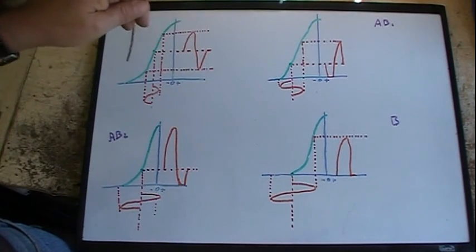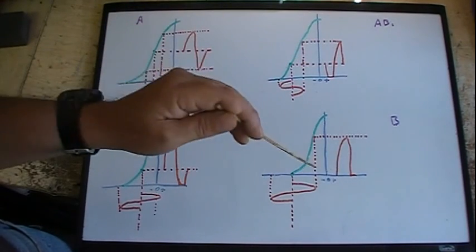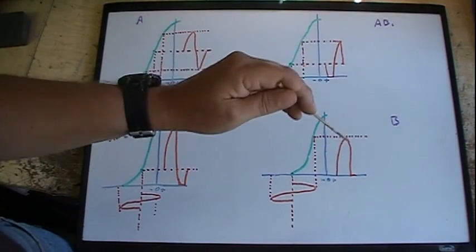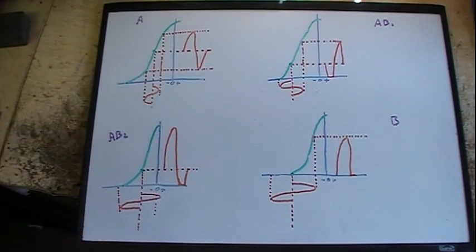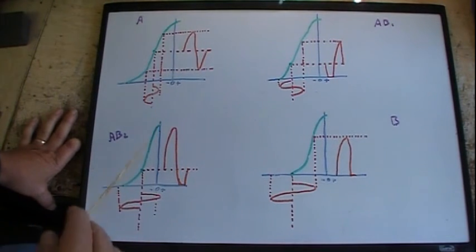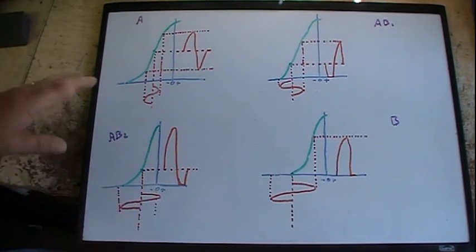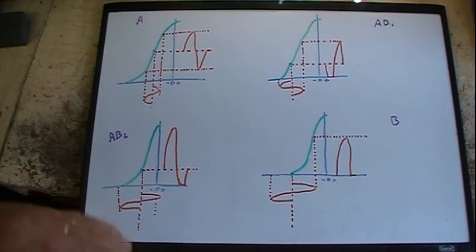Only one tube, the one getting the primary input, is amplifying, and on those you will find even harmonics, because you're only using one half of the audio transformer primary. But if you're using pentodes in that circuit, then it won't have any even harmonic, or very little anyway, depending on how good the audio output transformer is and how well everything's matched. And I'm not talking about tube matching. When I get into audio amplifiers, we're going to talk about tube matching.